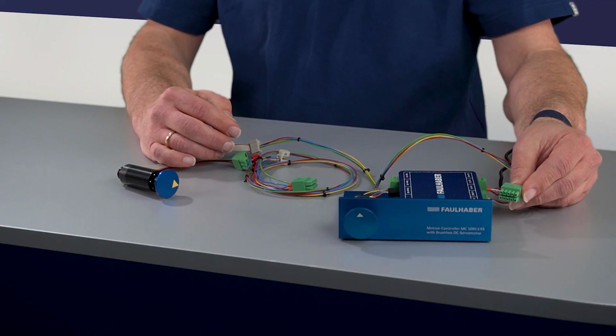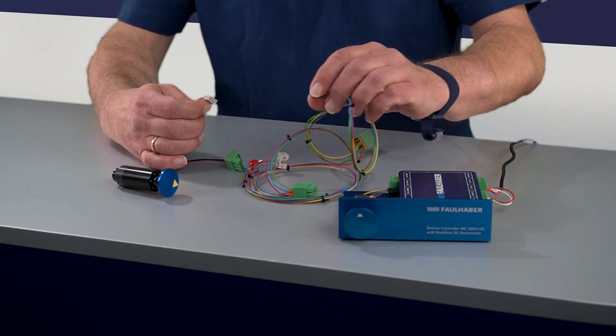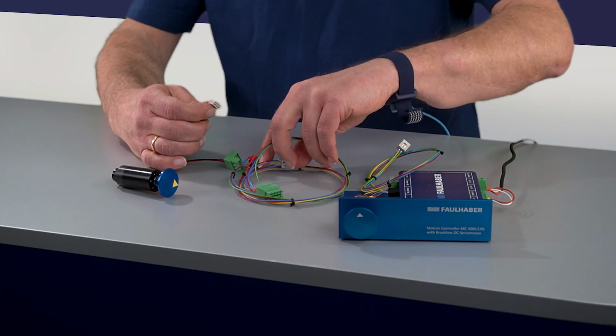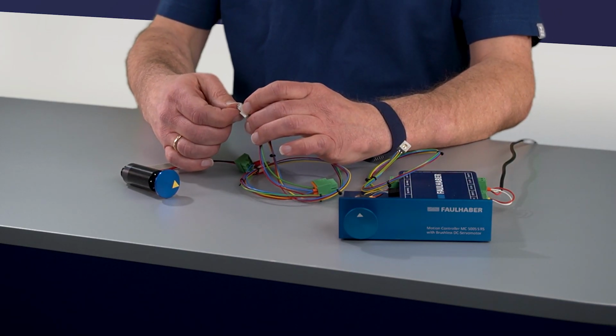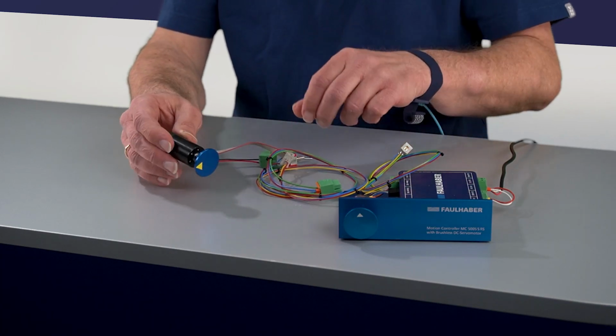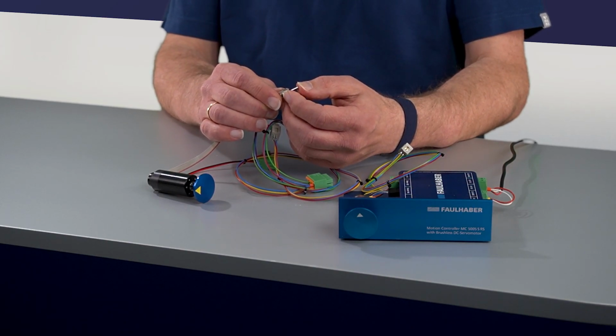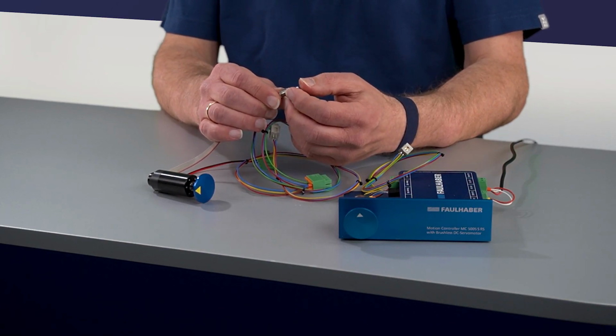So that's being used for the gearing mode, and for step mode I use the same encoder here, but only a single of these signals. So essentially then the encoder is only used to generate pulses, whereas a dedicated separate switch is used for the direction of the signal, so forward or backward. So that's the setup here. Let's switch to the PC. First, there are going to be two slides to explain what I have to configure, and afterwards we're switching to the live view of the Motion Manager.